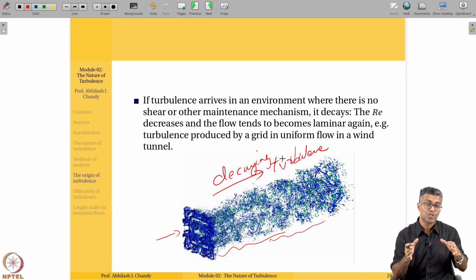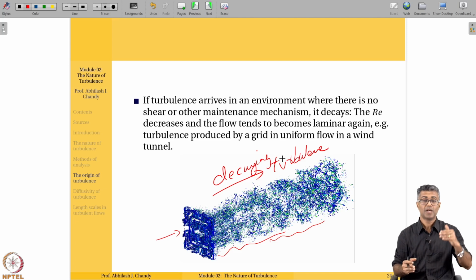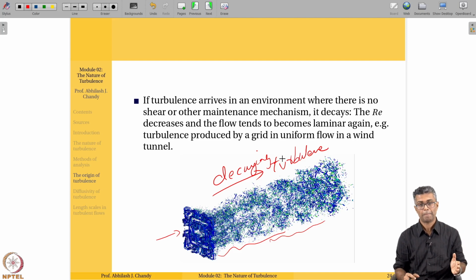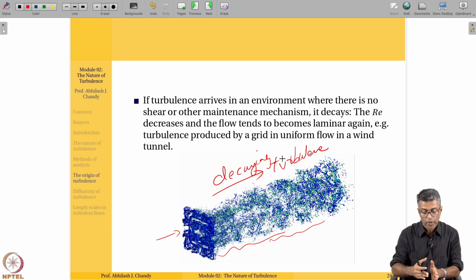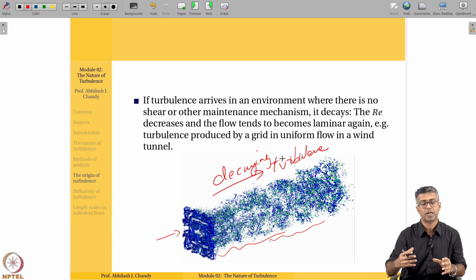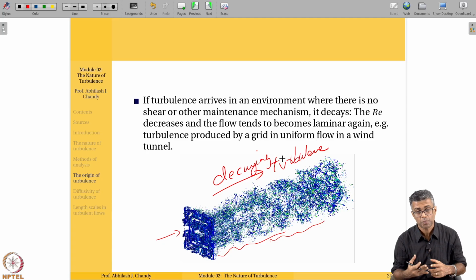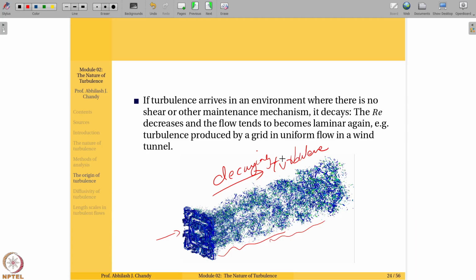This is what Taylor used as his hypothesis to convert the spatial data into temporal data. This was Taylor's hypothesis that I have discussed in module 1. It is this kind of data where the turbulence decays over space, and this could be converted into temporal data and used for several correlations, both for comparing computational models, for correlating with other experiments, and so on.